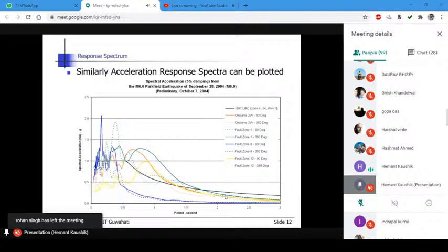It is very simple to understand because when you impart some flexibility to the system, the relative motion suddenly increases, right? So this mass starts vibrating vigorously, and obviously because of the amplification of the ground motion from base to top, the acceleration of this mass will be more than the peak ground acceleration.